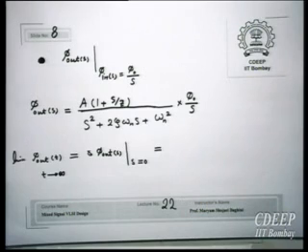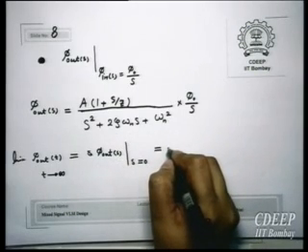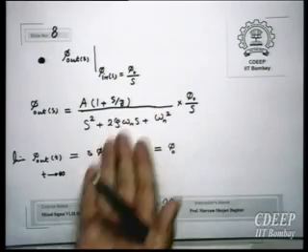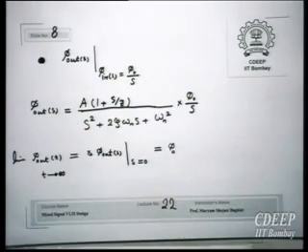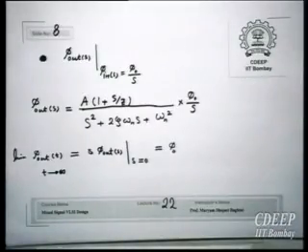What was the ratio? Ratio is 1, right? So this ratio A upon omega n square is 1. So this will be phi 0. Yeah, this is the same thing. Same. It will follow input. See, because if you multiply it by S, you will get the same transfer function by putting S equal to 0. I did the same thing, putting S here, 0. The same thing. Okay, so therefore error is not, error actually is 0.